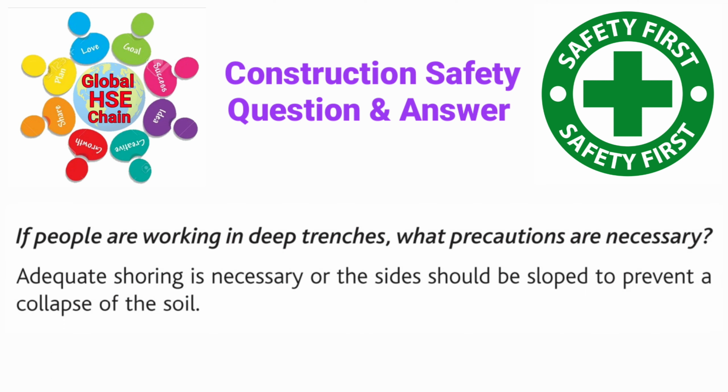Question is, if people are working in deep trenches, what precautions are necessary? The answer is, adequate shoring is necessary or the sides should be sloped to prevent a collapse of the soil.